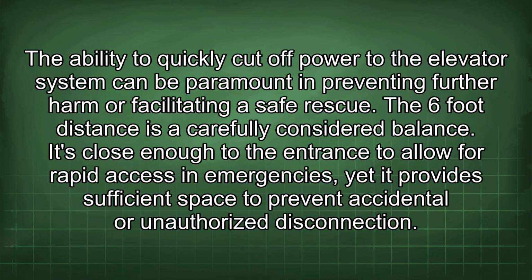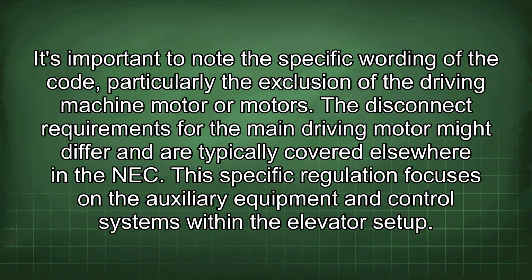The ability to quickly cut off power to the elevator system can be paramount in preventing further harm or facilitating a safe rescue. The 6-foot distance is a carefully considered balance. It's close enough to the entrance to allow for rapid access in emergencies, yet it provides sufficient space to prevent accidental or unauthorized disconnection.